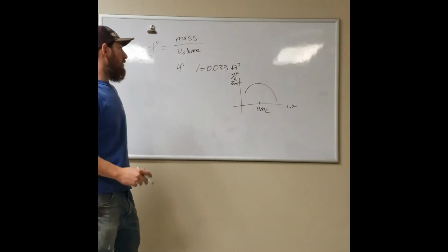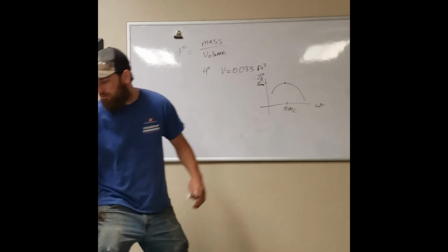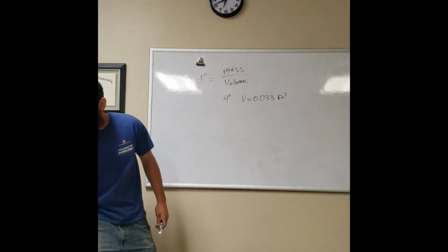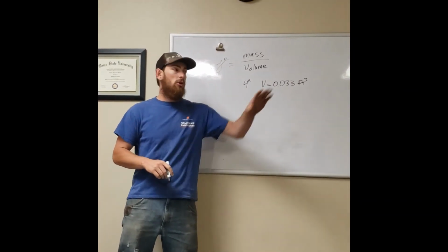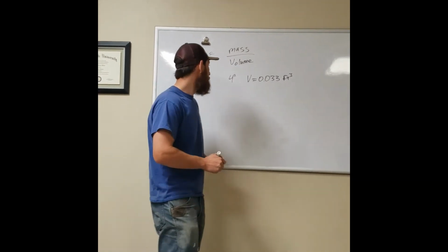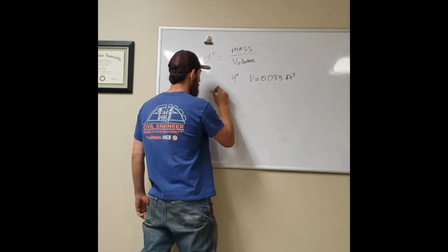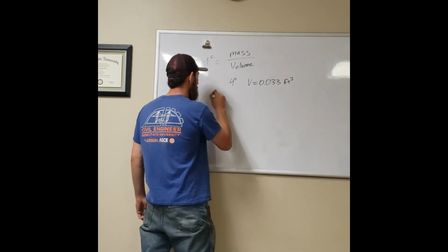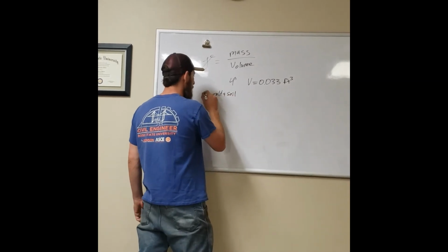The way that we're going to do this is I'm going to take a soil sample and add moisture to it, and we're going to be at a certain amount. I'm going to go through the procedure to add it up and compact it in a certain way. Now what I'm going to have is the mass of my mold plus soil, and this is wet.